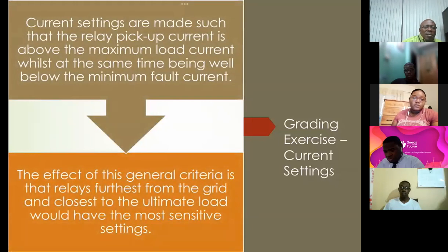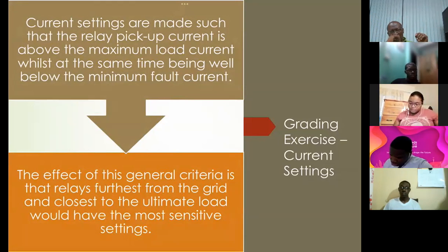So remember we spoke about discrimination, right? Keep in mind that we have already spoken about this. You want to ensure that the current setting is above maximum load, while at the same time below minimum fault current. So it must be above load and below minimum fault current.